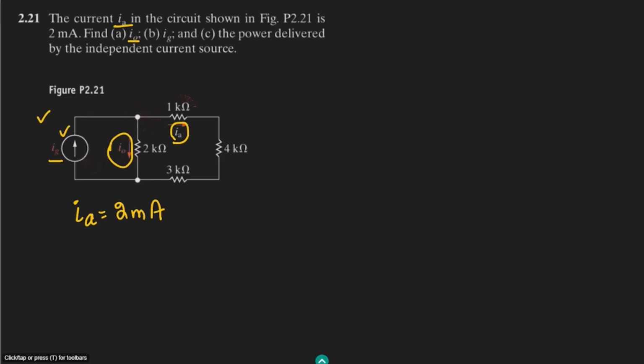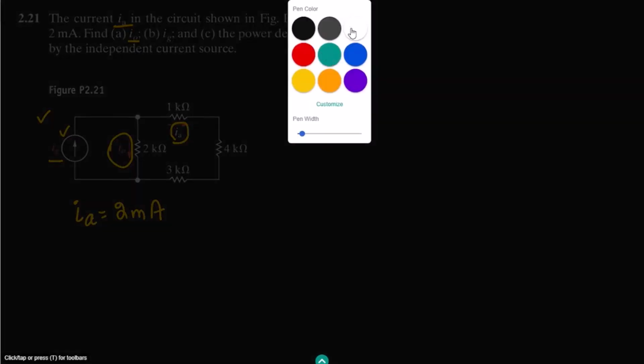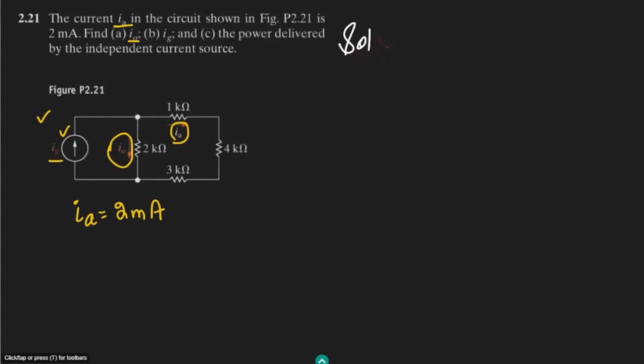Let us start, and in starting it, we have to find different quantities, and let me solve it here. Solution of it. First let me have here the KCL. According to Kirchhoff's current law, this current is flowing towards this node, which is here, and let me call it node A, and the current which is flowing towards it is Ig. And then it divides into two currents.